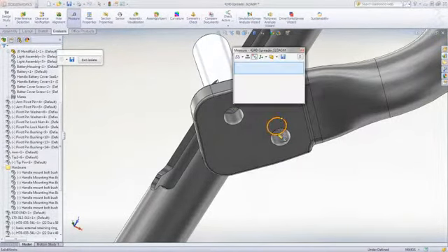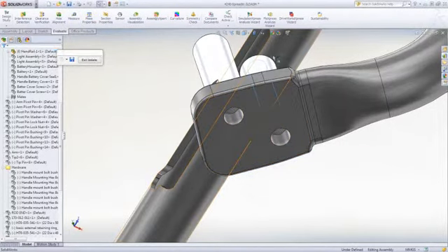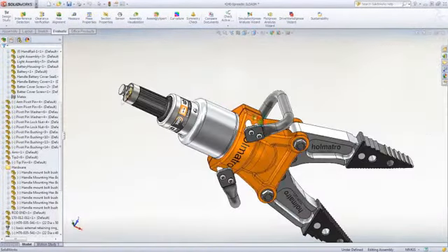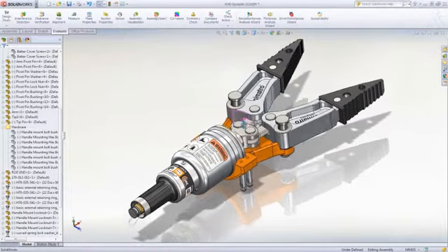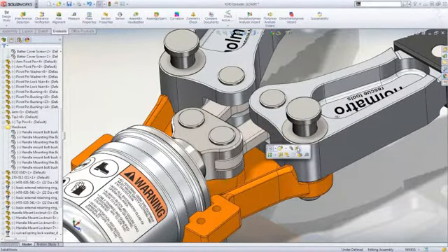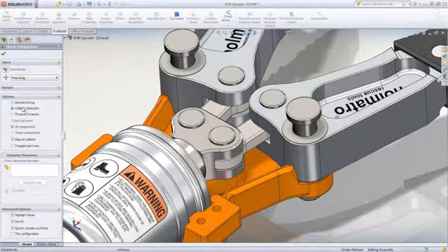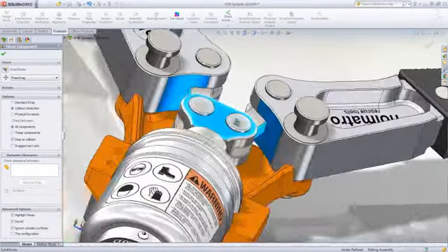The measure tool is quite useful for interrogating assemblies, and here it reports that our holes are now aligned. Interference detection makes sure that our assembly has the proper fit, but what about function? For this, we can use the collision detection capability. As we move the assembly through its range of motion, the travel stops when it finds a collision. Any colliding parts are highlighted, and we get an audible notification as well.